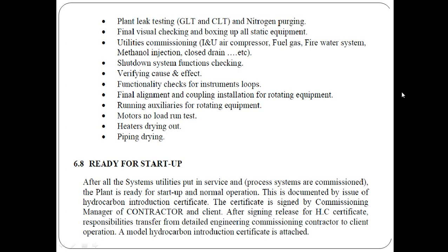This is documented by the issue of the hydrocarbon introduction certificate. The certificate is signed by the commissioning manager of the contractor and the client. After signing the release for hydrocarbon certificate, responsibilities transfer from the detailed engineering and commissioning contractor to the client operation.